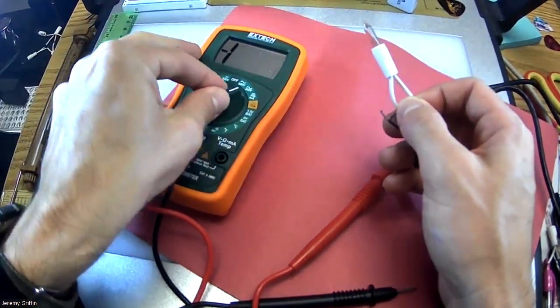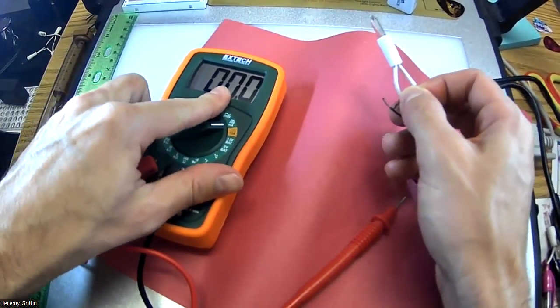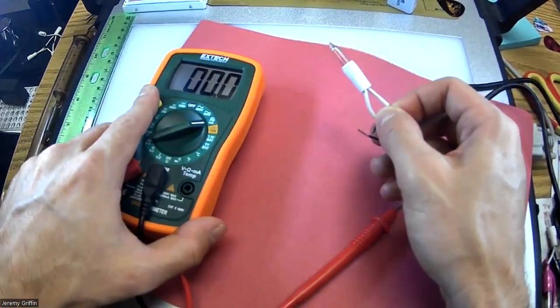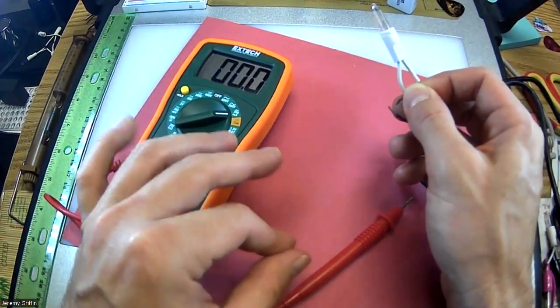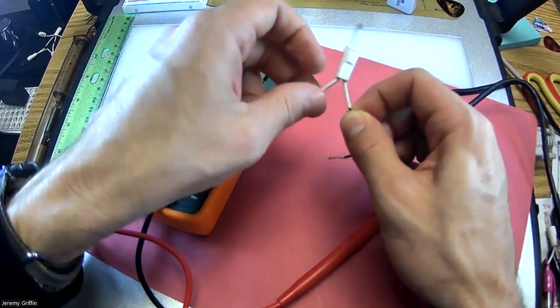Change this toggle over to the one that says milliamps. So how many amps is this going to be? Hey, I wonder what's the resistance of this light bulb, because we could probably use Ohm's law and whatever reading this shows to figure that out. There's one other change I'm going to do, which is I'm going to hook this up in series rather than parallel to measure current rather than voltage.